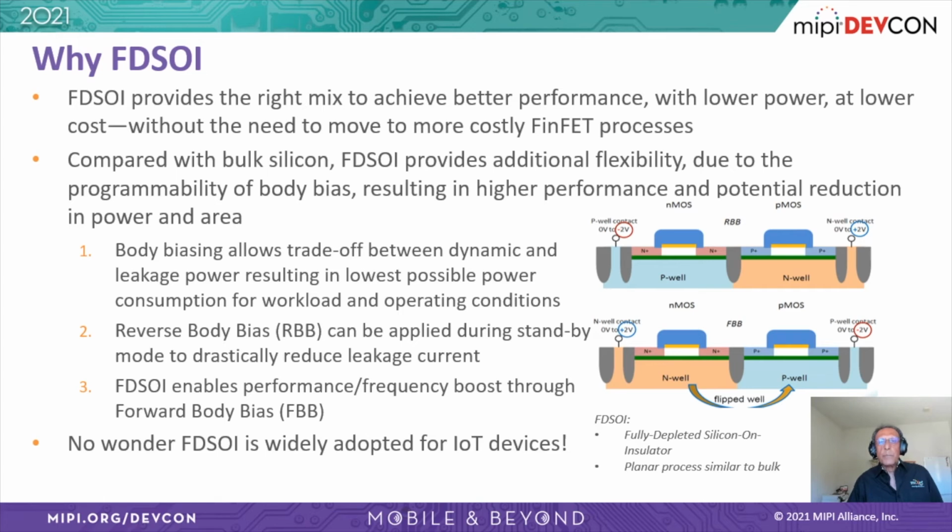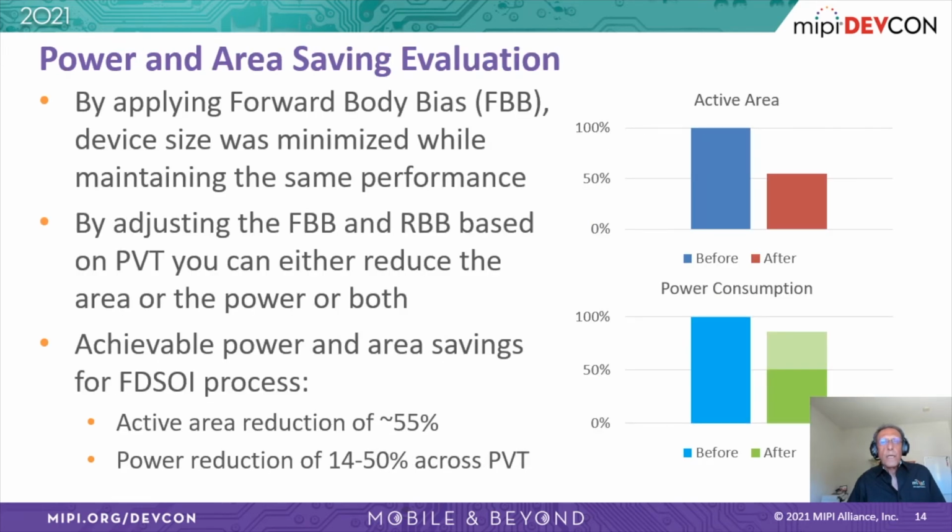FDSOI also enables performance and speed boost through forward body bias. It's no surprise that FDSOI is widely adopted in IoT devices. We conducted some analysis to quantify these benefits. In this evaluation, we applied forward bias to save area and reduce power.